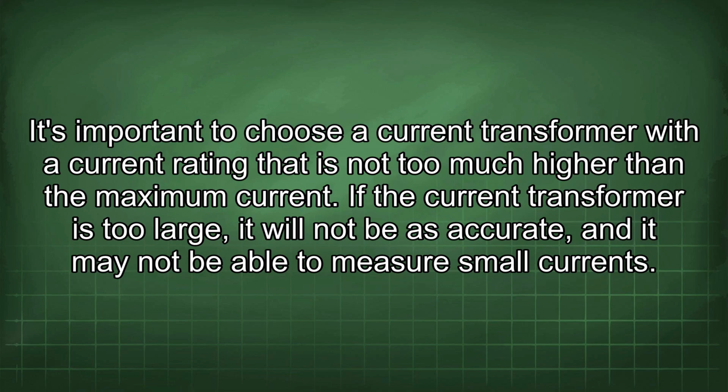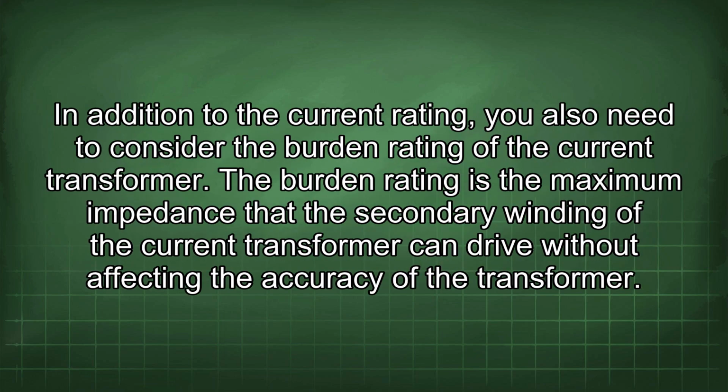It's important to choose a current transformer with a current rating that is not too much higher than the maximum current. If the current transformer is too large, it will not be as accurate, and it may not be able to measure small currents.